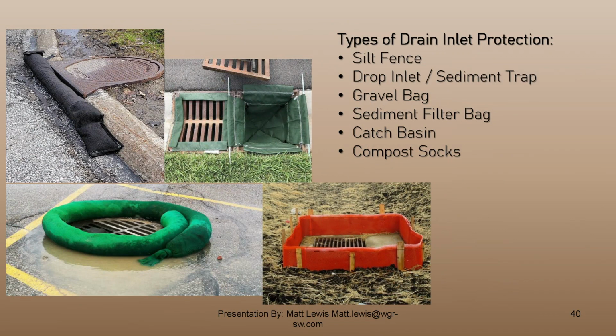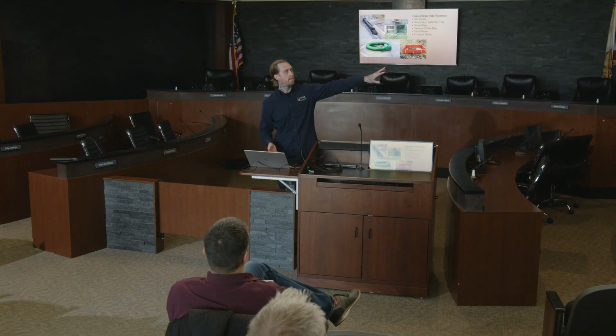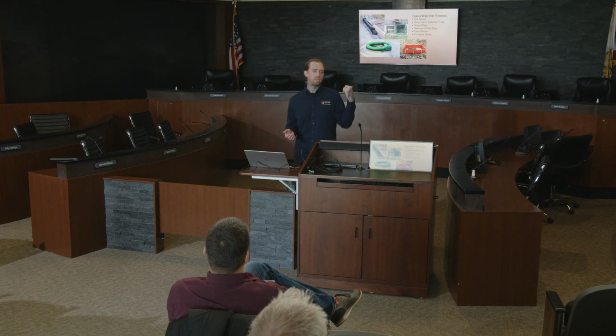Okay, into some drain inlet protection. I threw in some extra pictures, like this little orange silt fence thing. You usually don't see that too often. Generally what you're going to see is rock bags, which are almost never used correctly, and I personally hate them. My favorite is the green compost sock, because, number one, it's weighted, so even if you're using it on linear breaks or a perimeter, it doesn't have to be staked in like fiber rolls do. And fiber rolls, for instance, don't allow penetration of water.